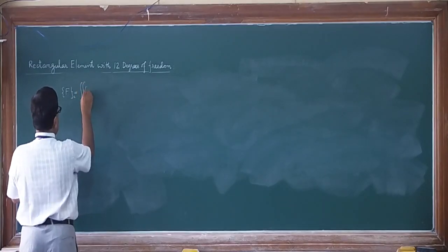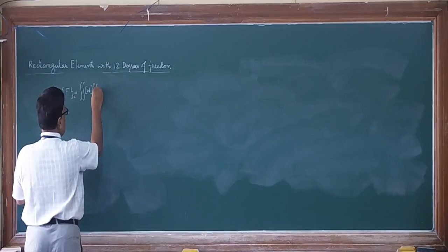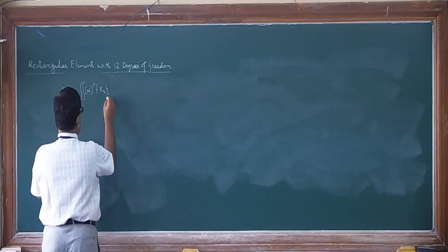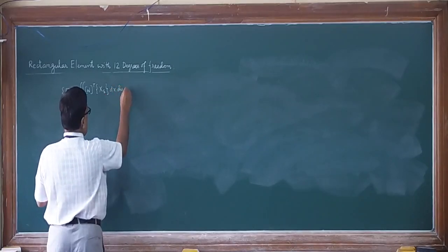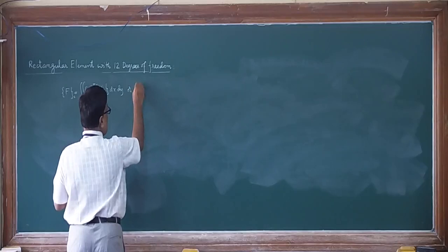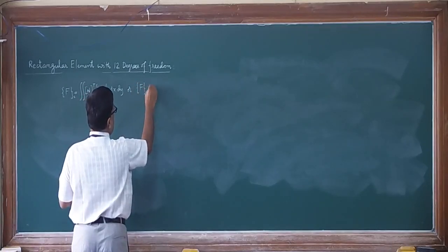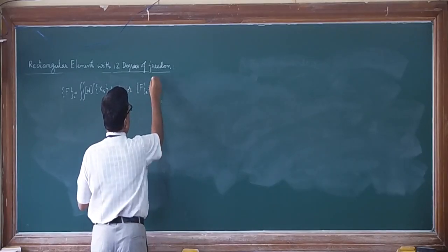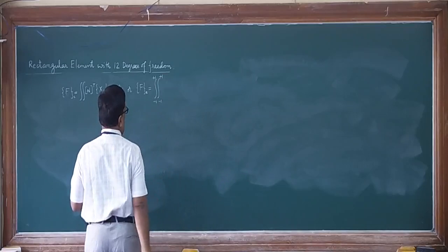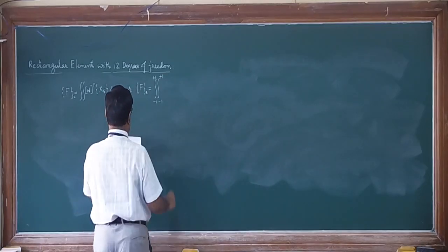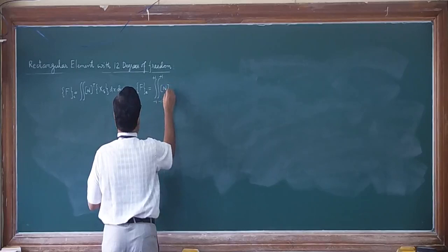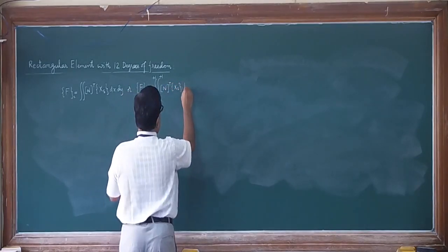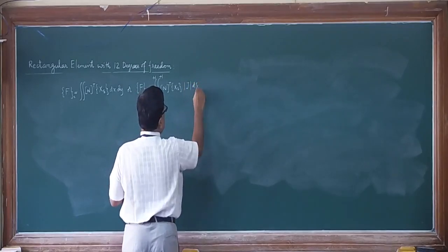It is double integration N transpose Xs dx dy, or you can also write F can be written as Fe. If you convert this into natural coordinates, the integration sign will change from 0 to L to -1 to +1. This will get N transpose Xs determinant of J into d zeta d eta.